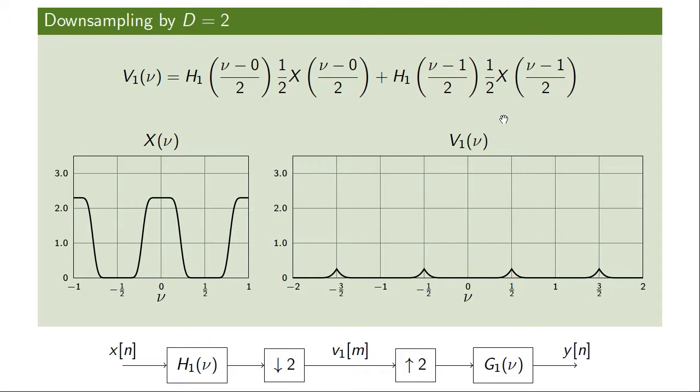So essentially what we have in this range from -1/2 to 1/2 is no longer a representation of the frequencies between -1/4 and 1/4, but instead a representation of frequencies in the higher frequency range, even though the frequencies within this range do not correspond directly to these, but they correspond to a mirrored version of these higher frequencies. And you can see that it's this part of the spectrum which ends up here, and it's this part of the spectrum which ends up here, also scaled both in amplitude and in terms of frequency.